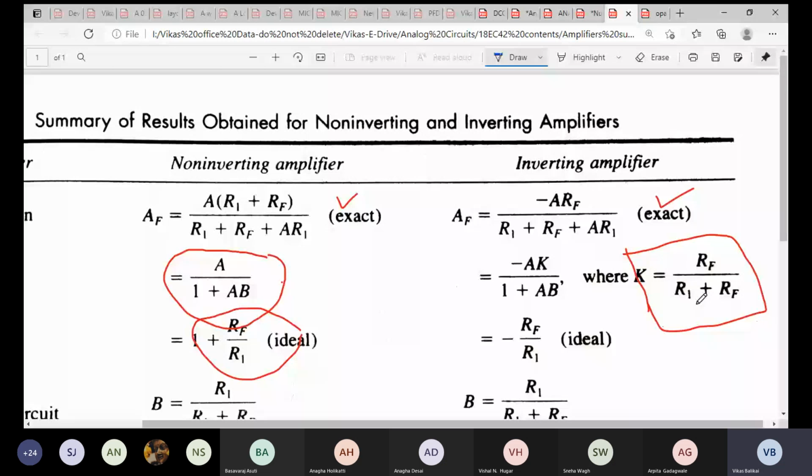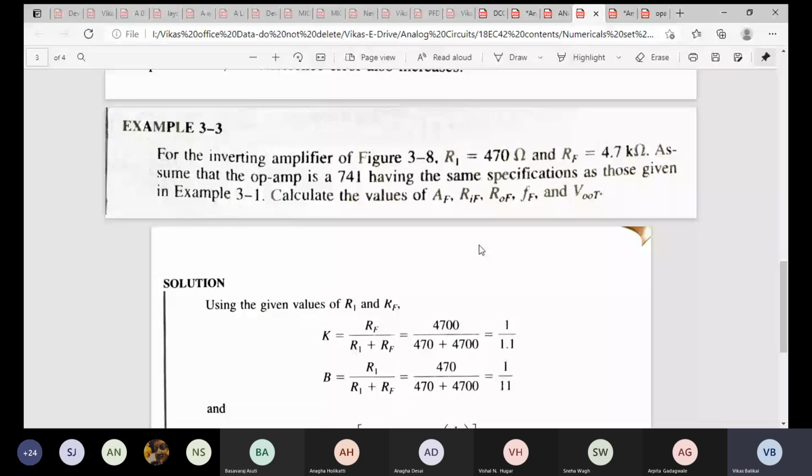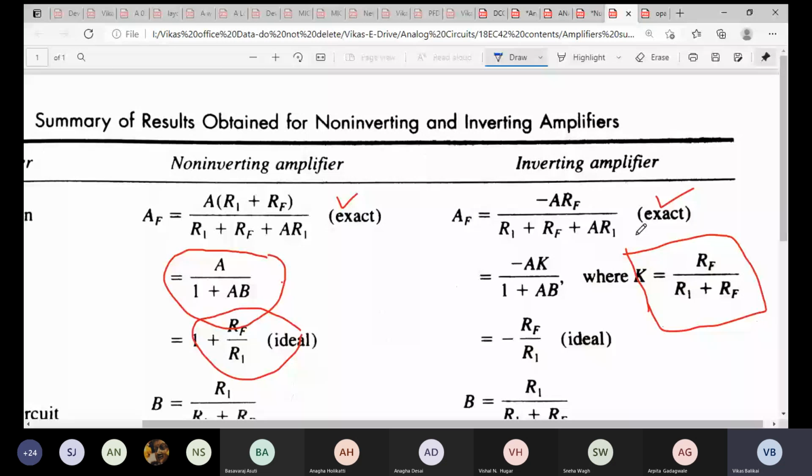Regarding the attenuation factor, whenever we talk about the amplifier, when output is getting back to the input through the feedback, there is one feedback resistor and there is another resistance R1. So there is voltage division between R1 and RF: one voltage goes to the input side, and one voltage will be lost. So it leads to attenuation in the feedback. To identify the attenuation factor, he has taken up this particular equation. So this equation I should always remember, specifically in the inverting configuration only.